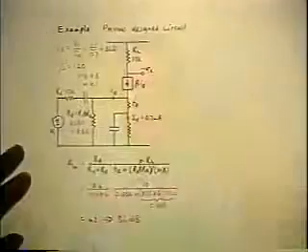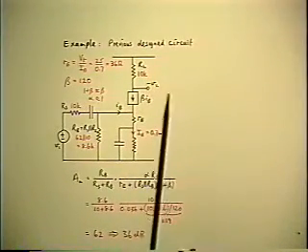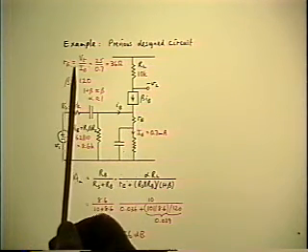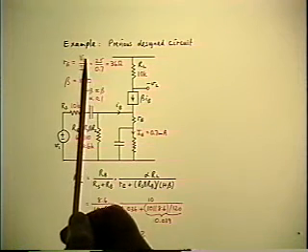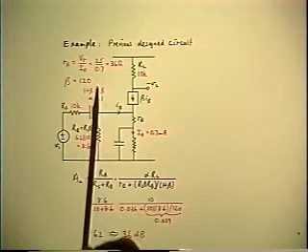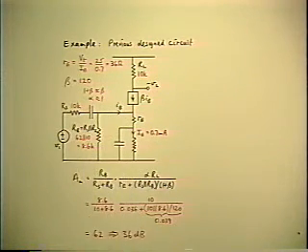Different ones may be better for calculating different things. The main thing is, remember that you have the power to get different versions that may be more helpful. Okay, to pursue this through to the end now, here's a typical set of numbers. The only noteworthy point is the value of the RE, which I mentioned. The formula for it is the thermal voltage divided by the emitter DC current, which in this particular case is 0.7 milliamps, so the RE comes to 36 ohms.